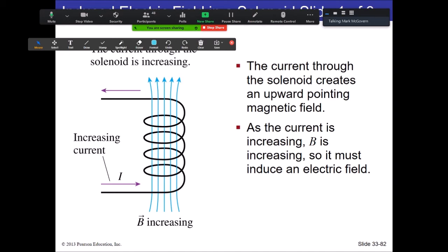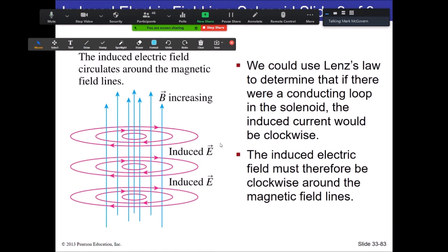in addition to the field that already exists that's pushing the current through. And this is a very important element of things we're going to be talking about, I think, in the next lecture called inductors, which is exactly this principle here. The change of magnetic flux to the solenoid creates what we call a back EMF, an EMF that exists across the solenoid that acts as basically a resistive element. Or if the current is decreasing, that actually will encourage more current. And so it could be a resistive element, or it can be a source of potential, actually. Actually can drive current. So we'll see the details of that a little bit later, though.